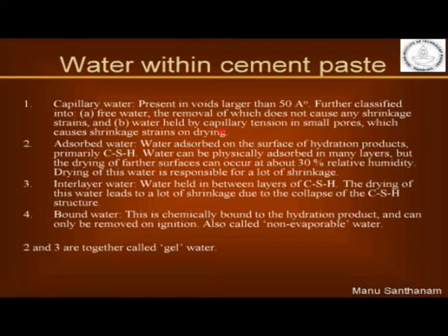But if you have a very thin capillary pore and you are trying to dry the water out, it is going to produce extremely high capillary pressures and lead to very high levels of shrinkage.